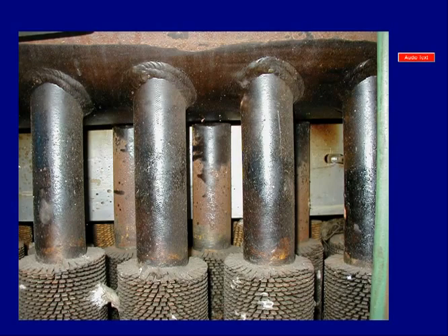The HRSG is primarily composed of finned tubes. The outer side of the HRSG tubes are covered with fins. These fins are designed to enlarge the tube's surface area to increase the rate of heat transfer.